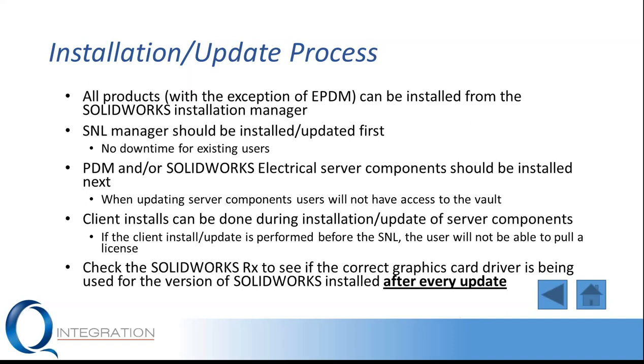I would say after we update our Network License Manager, we should take a look at our server components being installed. So things like PDM, our electrical server components, because we can update these server components and still go in and then update the clients as well. And I think the clients take much longer, so I recommend going through and upgrading the server components first.